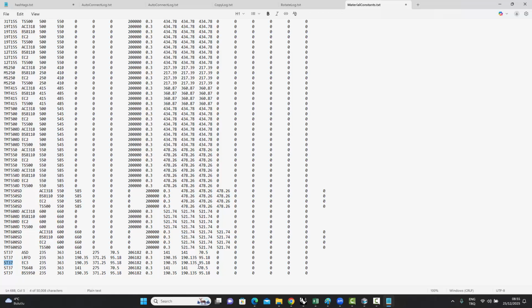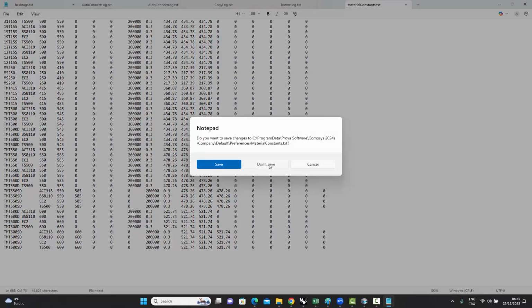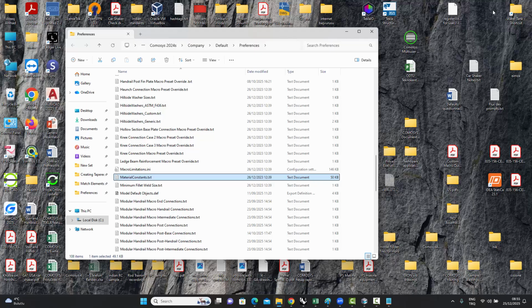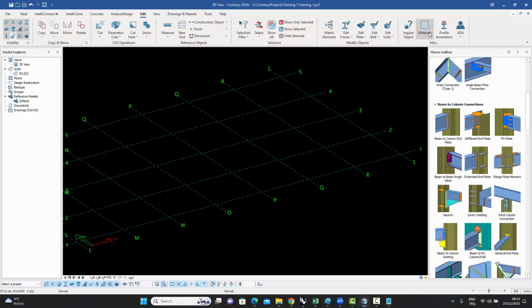which you want the macros to use in the preliminary design, and then the macros will start using those numbers in the preliminary design. If you don't do that, then the macros might give you some error that the material is not found or something like that. So just a precautionary note: when you add a new material, things won't stop, you can still continue working. It's probably going to use some default values or something. But the best option is to immediately go to the material constants file as well, add 5 lines for that material and change the numbers for each line.